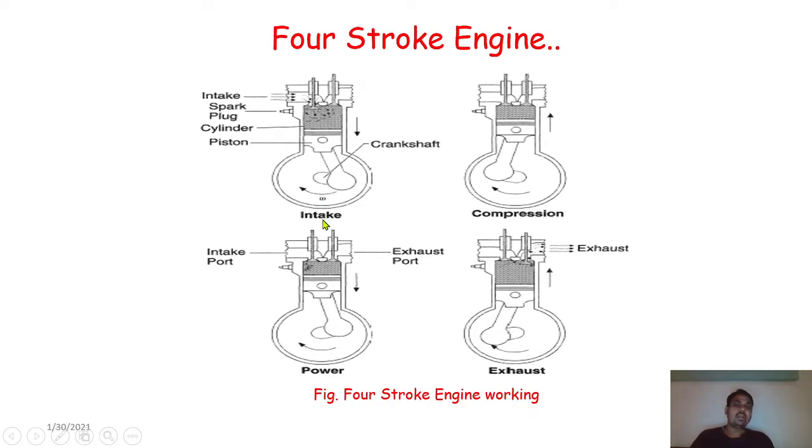So during this suction process, the revolution of the crankshaft is half a revolution, or we can say it will rotate 180 degrees. So this stroke will happen within half a revolution, or 180-degree rotation, of the crankshaft itself.